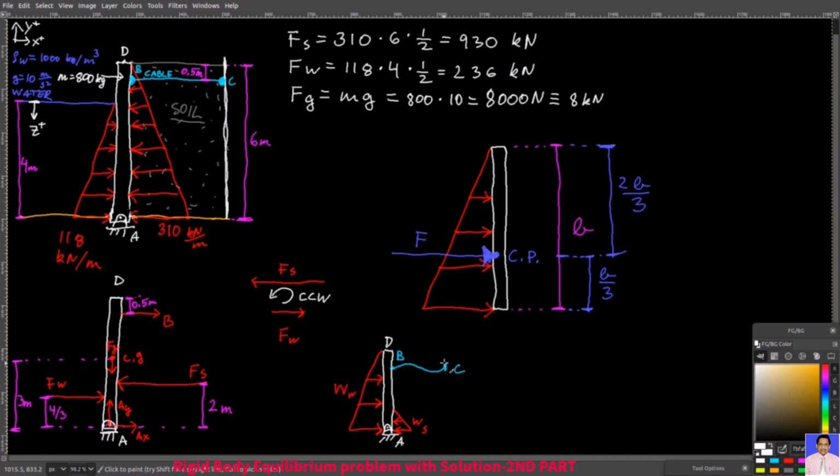In that case, instead of a cable, you could put a solid rod there. A solid rod can resist motion when it's in compression. So in conclusion, you have to be careful when you use cable support. You must be sure that the loading situation does not change in such a way that the cable ends up being in compression. It can be very dangerous.